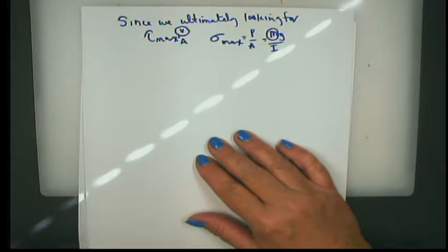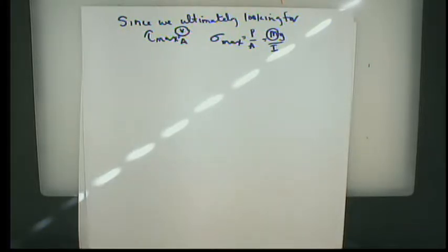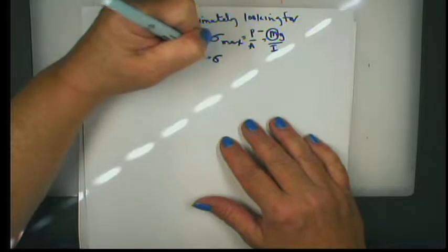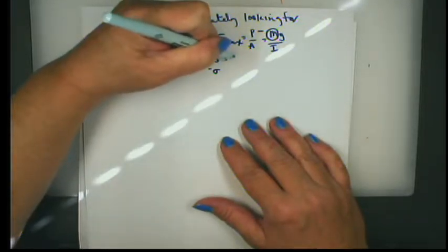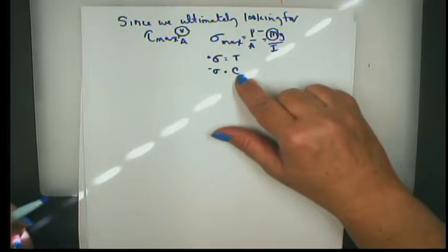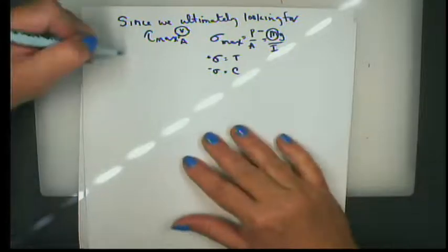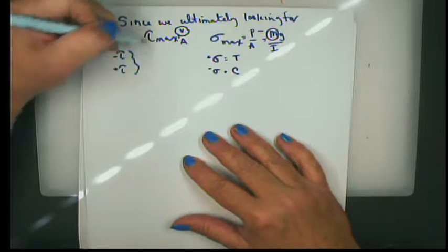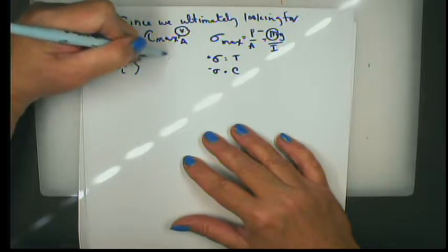We want to know the magnitude of V across a beam, and we want to know the magnitude of M across a beam. So the other thing to think about here, we have a different meaning when we have positive sigma max, or positive sigma or negative sigma. Positive sigma means tension, negative sigma means compression. And they are two different physical phenomena, aren't they? Well, if tau is negative or tau is positive, it's the same physical phenomena.